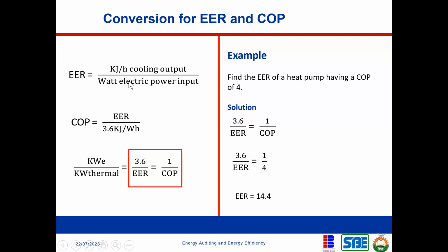So you have to convert both of them to a common unit. But this is something you can read up. The most important thing is what I have just highlighted here, which is this equation that you can use to convert from COP to EER. And like I said, this is just for examination purposes. Most often, you might not do all of this when you go to conduct industrial energy audits.